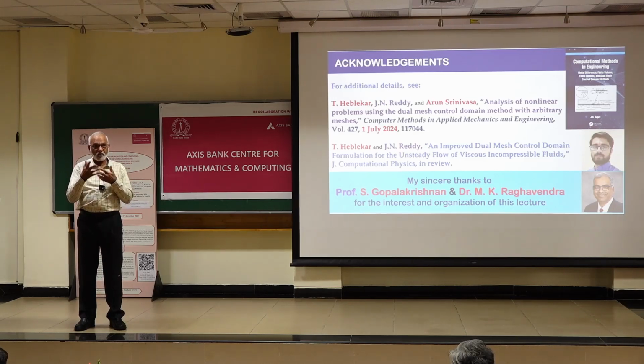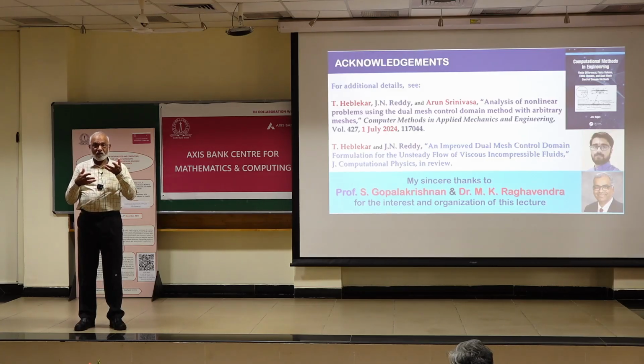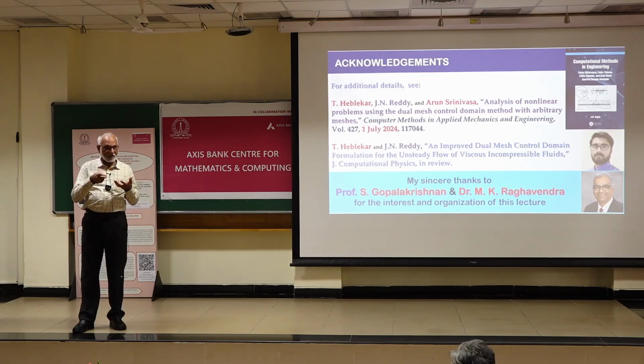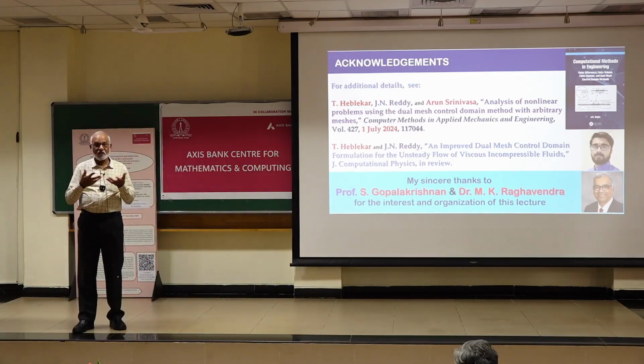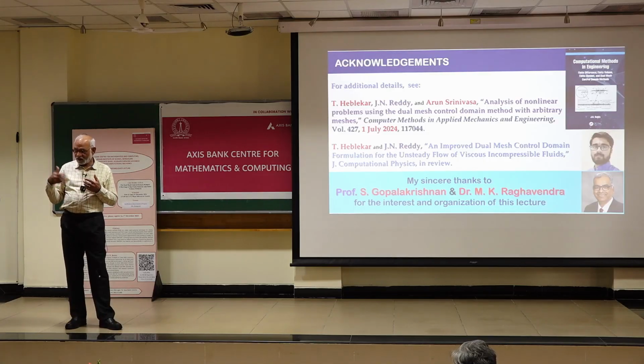Suppose you have a mixed formulation of elasticity. Then you have stresses and displacements, and they are not the same. Displacements are a higher degree differentiable field compared to stresses. Stresses need only one derivative according to the equations of equilibrium, whereas Navier's equations of elasticity require two derivatives. So if you say I'm going to use the same degree of interpolation for stress and displacement, then they don't join. This is where locking comes from. So by using higher order interpolation, we get rid of the locking.